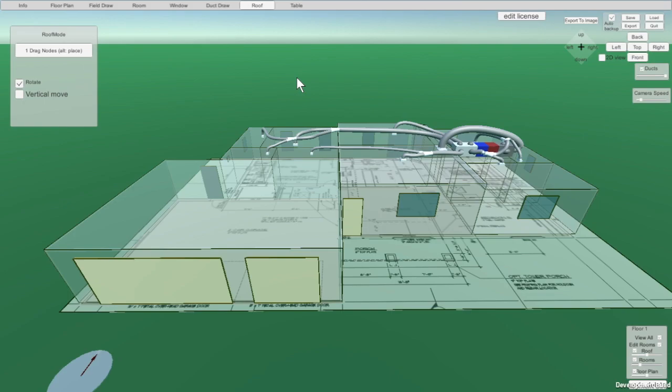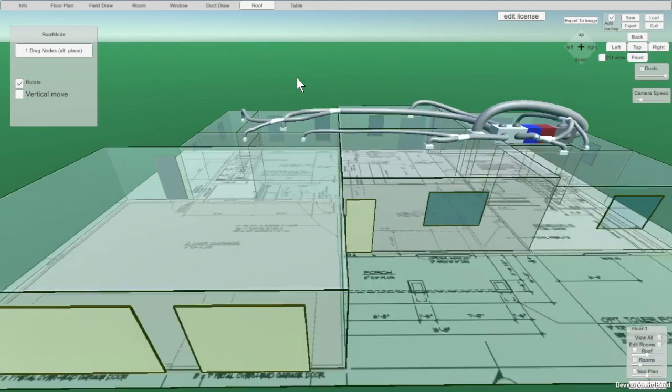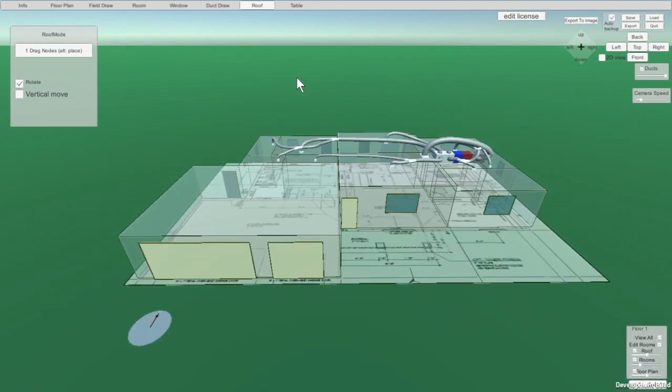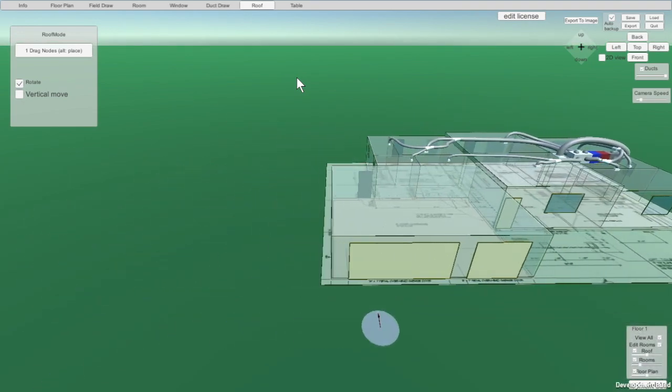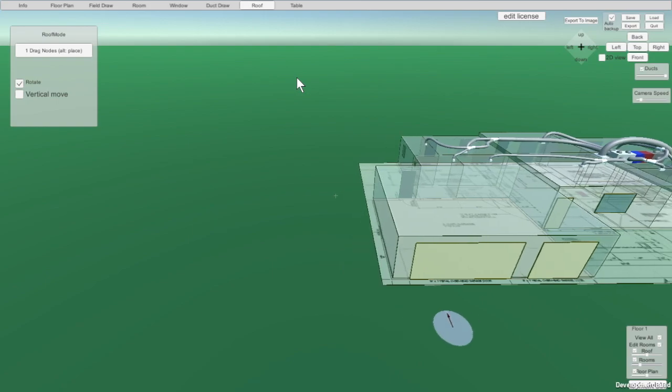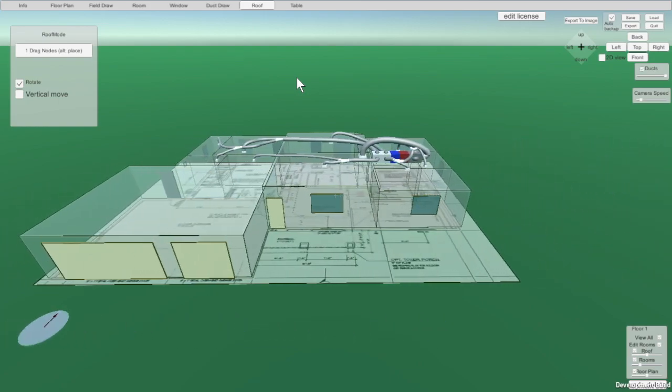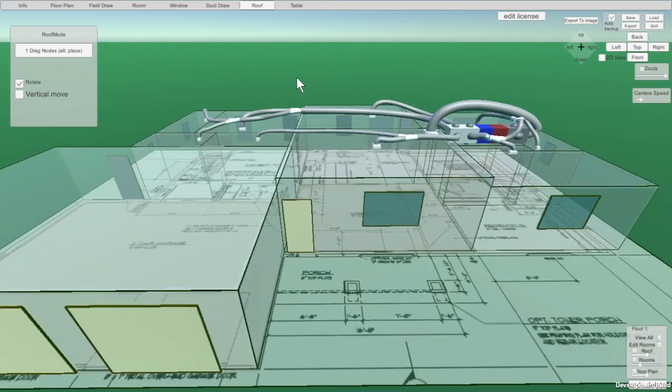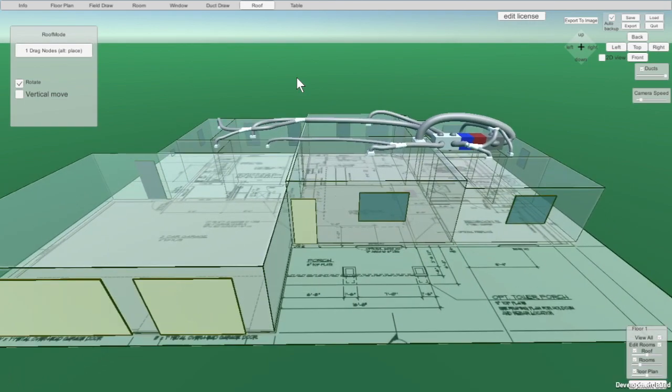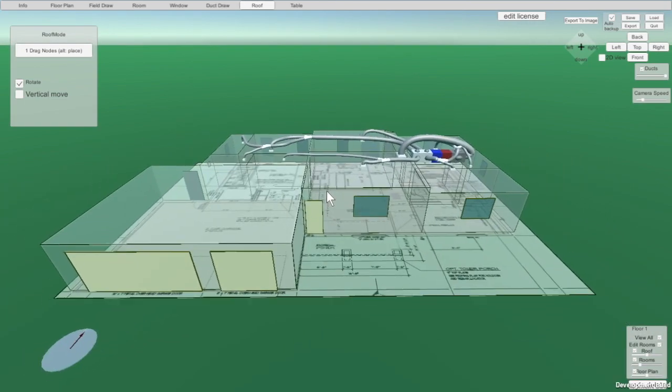The other thing that's not shown anywhere is kind of secret buttons. It's very common buttons used in video games, and that's if you put your left hand with your middle finger on the W, S, A, and D. W pans in, S pans out, zooms, and A pans and D pans to the right. A pans to the left, D right, W zoom in, S zoom out. So it's a little faster than the scroll wheel.